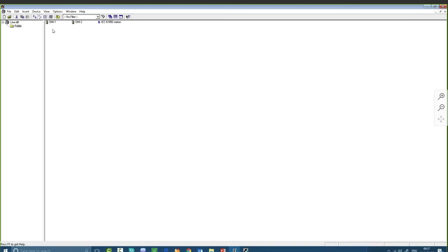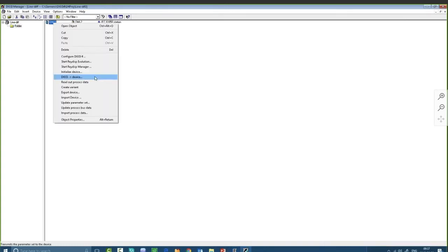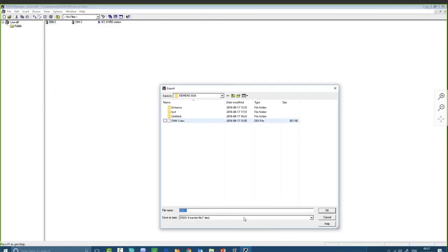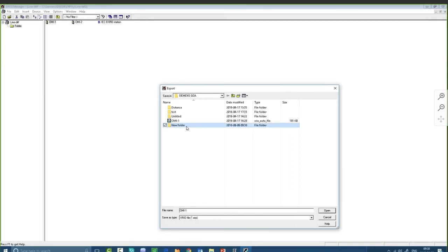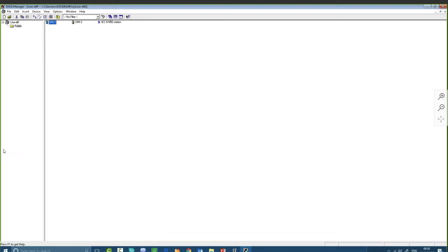Now I will start with Siemens. First of all, I can export directly from here. And please, you have to select XRIO. Now we have the XRIO format you can export. Let me make one folder. Okay, this will be our target. Relay name 7SD. Now we are finished.